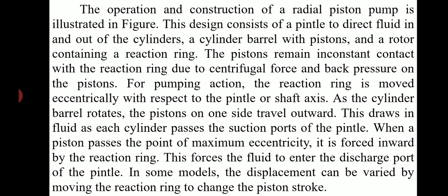For pumping action, the reaction ring is moved eccentrically with respect to the pintle or shaft axis. As the cylinder barrel rotates, the pistons on one side travel outward. This draws in fluid as each cylinder passes the suction ports of the pintle. When a piston passes the point of maximum eccentricity, it is forced inward by the reaction ring. This forces the fluid to enter the discharge port of the pintle.